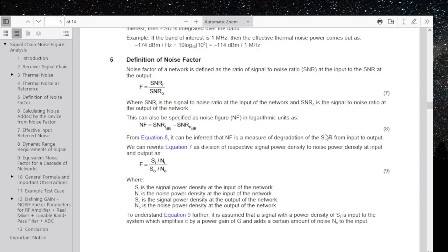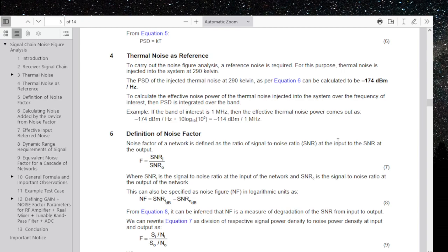Yeah. Well, you've got to have references to go by. So if we can have a noise setup in a differential amplifier type circuit or a comparator circuit of some sort, it's actually two op amps, one running positive, the other one running negative, and the positive and negative sides of the op amps are connected together, and one is the noise, the other is the noise plus the signal. Theoretically, the noise cancels. Theoretically, because it's the same noise.